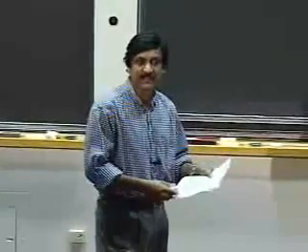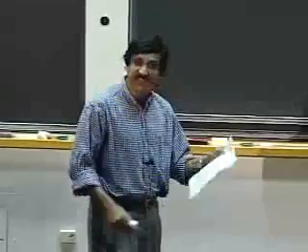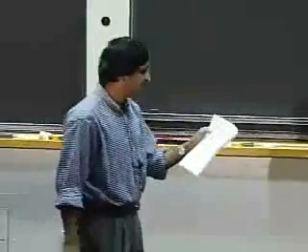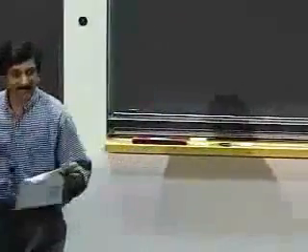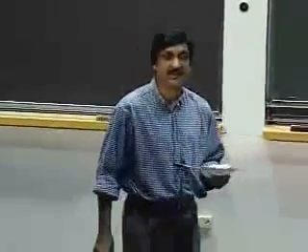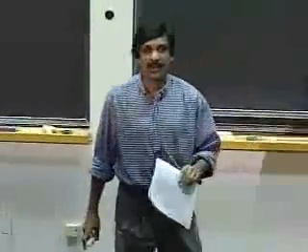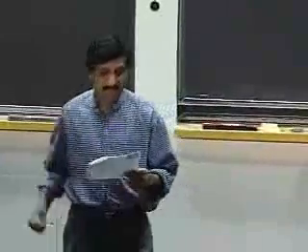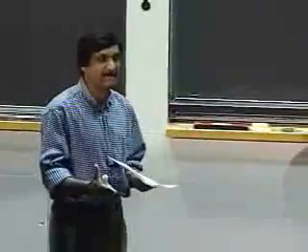Well, we'll find out. The second thing I've circled is something called power dissipation. Power dissipation is said to be 0.006 microwatts per megahertz per gate. So it says power dissipation is 6 nanowatts per megahertz per gate.